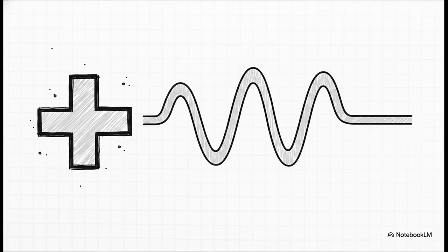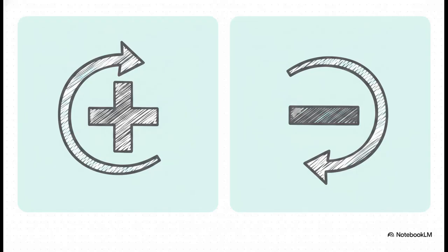Let's zoom in on that positive sequence network for a second. It's used in the analysis of symmetrical faults and really forms the foundation of load flow studies in the power system. It's essentially the same as the standard sequence reactance or impedance network. So the crucial point I want you to take away is that this positive network acts as the baseline. It represents the normal, healthy operation and power flow of the grid. Now, when we contrast the positive and negative sequence impedances directly, we realize they're remarkably similar in structure. The defining difference is purely mathematical. The negative sequence network carries the exact opposite mathematical sign to that of the positive sequence impedance.